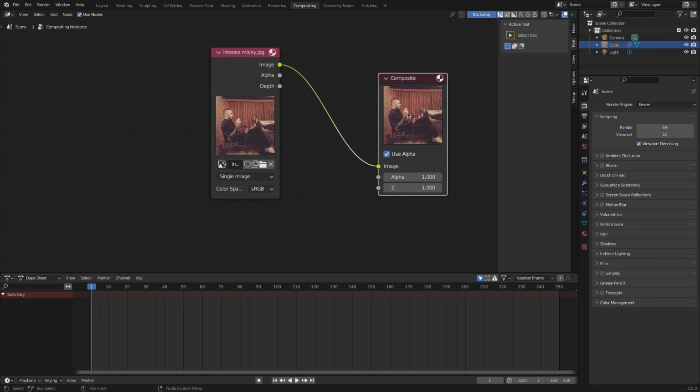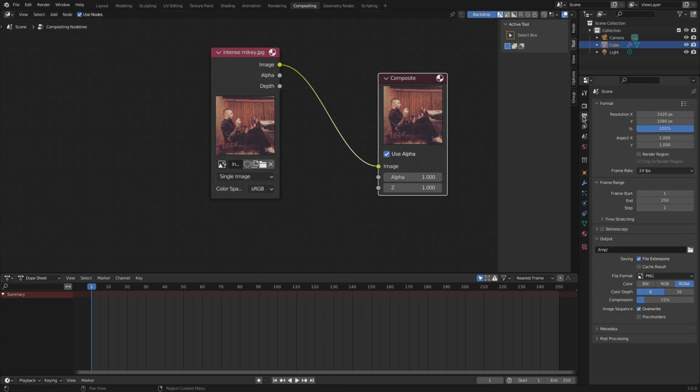All right. This document does talk about read render layers. I feel like it's possibly a little too deep, but there's the shortcut Control R, which is read render layers. This only works in the compositor. And for it to work, you need to have cache results selected.